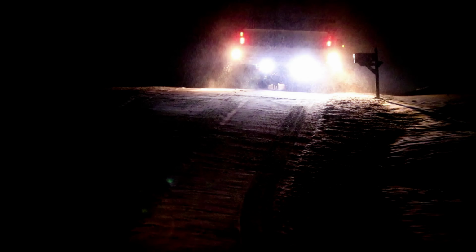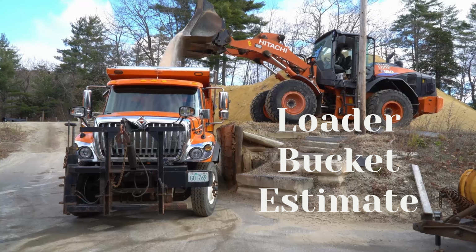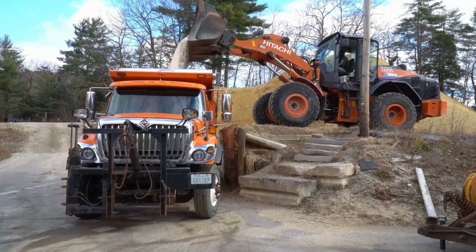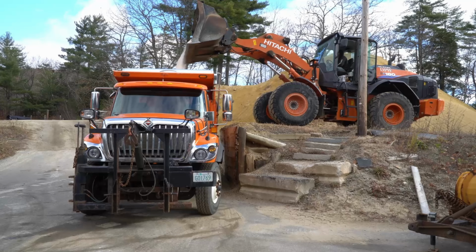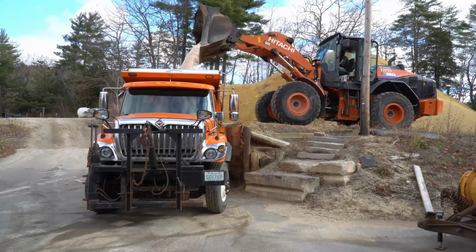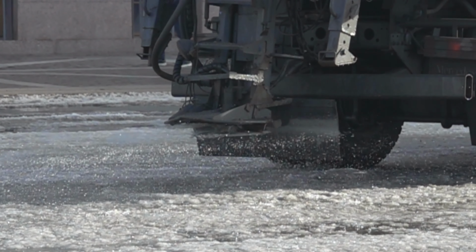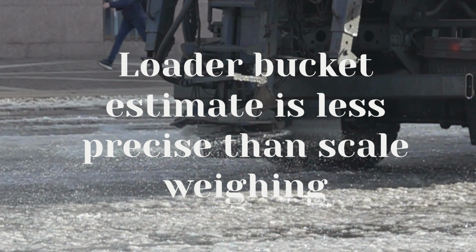If scales are not available, a loader bucket estimate of what you start and end with can provide a practical field check. For example, if your loader bucket typically holds about 3 tons of salt, one full bucket would contain approximately 6,000 pounds of material. If you returned with about 1/3 of a bucket remaining, you would estimate roughly 2,000 pounds still left in the truck. That means you used approximately 4,000 pounds, or 2 tons, during the route and could compare that to your miles treated and expected usage.